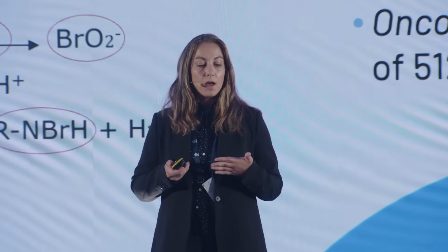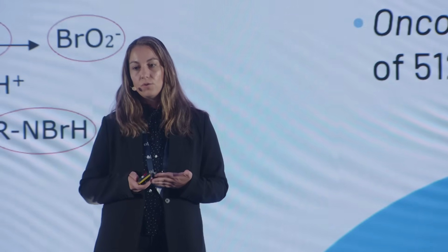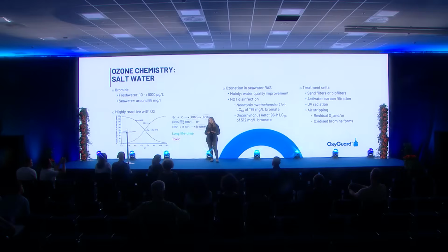We have to keep in mind that when we ozonate saltwater systems, we do it in order to improve the water quality and not to disinfect, because in order to disinfect, we need much higher ozone dosages, and that means that the risk of creating all these brominated byproducts increases significantly.